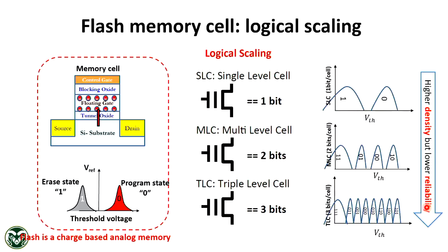So that's a very good question. There is a reason, a very strong reason. It is called Gray encoding. There is a pattern for it. For example, if you go from 00 to 11, the problem is if a cell threshold voltage drifts, 2 bits would be flipped, because you are going from 00 to 11 or 01 to 10. So you don't want 2 bits to be flipped because of some cell mistake. So here, only 1 bit is changed. You can see 11 goes to 01, 01 goes to 00, 00 goes to 10. So between 2 adjacent states, only 1 bit position is different.